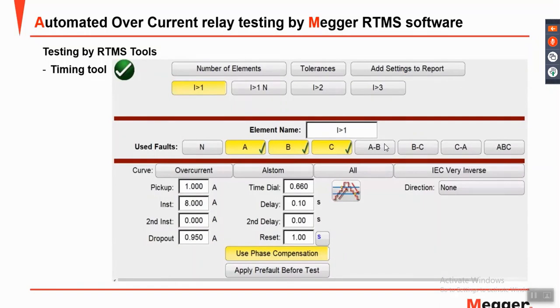Now, for example, I choose here stage 1 and then stage 1 neutral, stage 2 and stage 3 fire. We choose the relays we need over here, and if there is a neutral combined, then we don't need to turn off the neutral or do anything. We just choose something called current compensation to always cancel your neutral current.